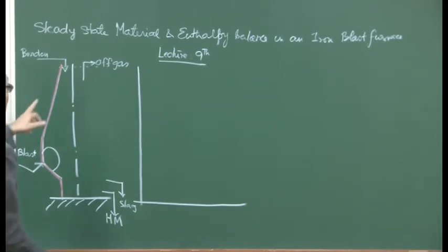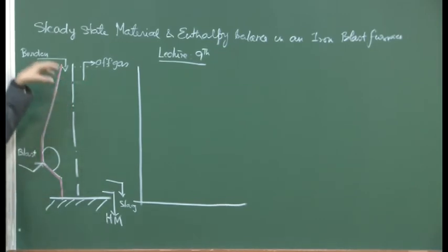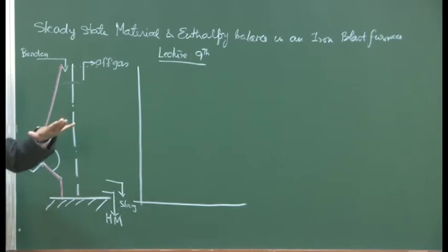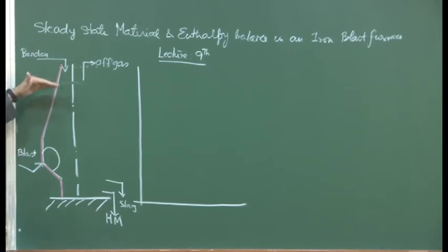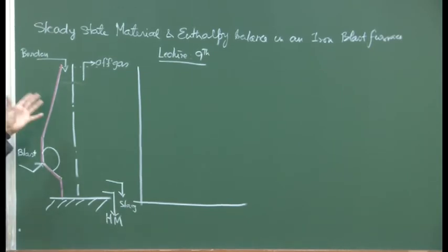For example, the stock level of the charge is controlled by a profilometer. The laser signal from the surface is fed into some sort of algorithm, and then you find out how much the stock level has gone down and how much material you have to charge in. That is a sensor based program to find out where the stock level has gone down, and how much material you have to charge, and so on.